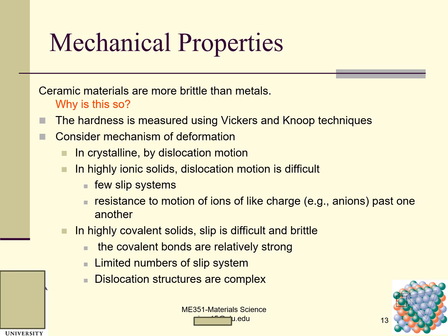Right? And then the Vickers and Knoop techniques, these two hardness testing techniques, are for microhardness testing. This is for ceramics. We need to use Vickers and Knoop techniques.